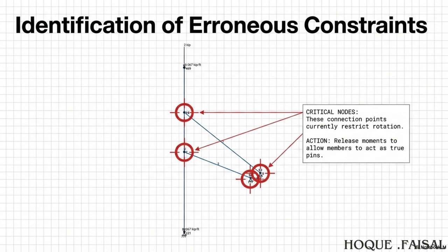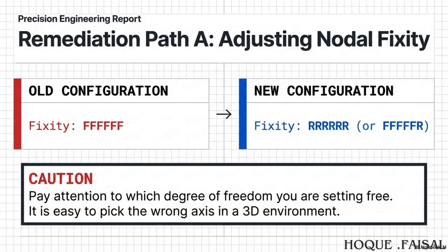We have node 221 at the bottom at y equals 0, and node 469 at the very top, y equals 24 feet. The full height of the structure. And then these braces connect at different heights. Member 1 connects a node way in the back, node 8, up to a point high on the stud, node 55. It creates a triangle. Exactly. Member 3 does the same thing lower down. It's a triangle. And triangles are good. Triangles are strong. On paper, the geometry makes perfect sense. It looks like a completely standard formwork support system you'd see on any job site.